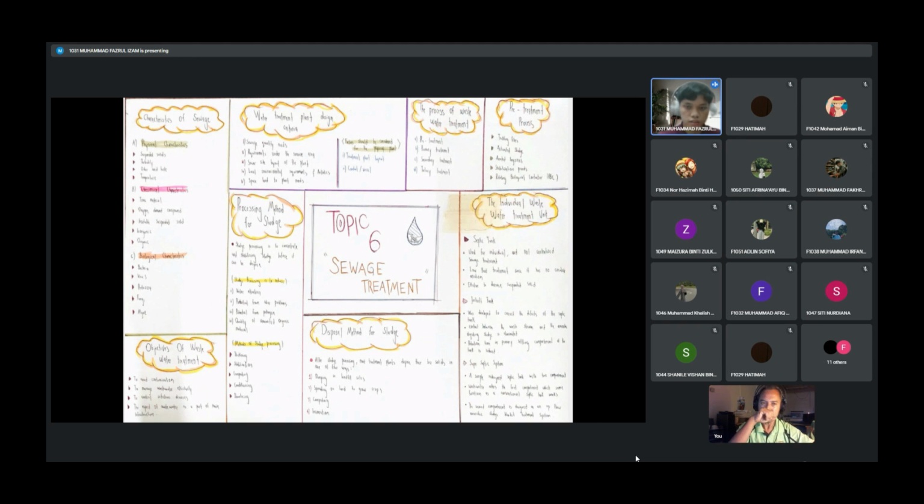Firstly, we will see the design criteria for domestic sewage treatment plant, and then we learn about the principle of preliminary and primary wastewater treatment, and then the biological sewage treatment process, and some of the process about the trickling filters, oxidation ponds, activated sludge, and rotating biological contactor. And lastly, in this subtopic, we will also learn about the effect of poor biological treatment on the environment.